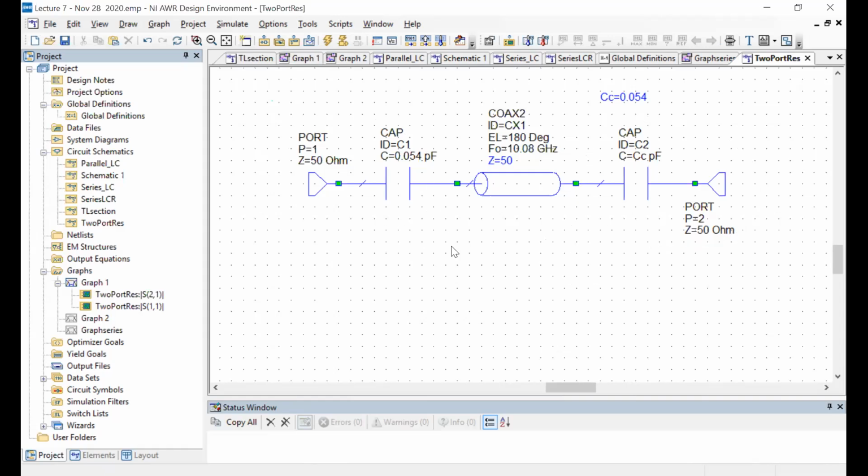But this is just to get a sense of it more practically. This is what you need to know: if you want the signal to transmit with unit transmission, then you need to make the two mirrors symmetric. This is a choice one makes when designing resonators, because often resonators are of this type, and you need to choose these two coupling capacitors, and you have to make them equal if you would like a symmetric resonator.